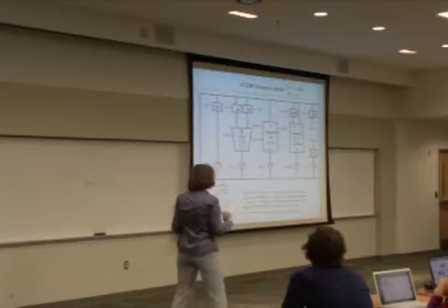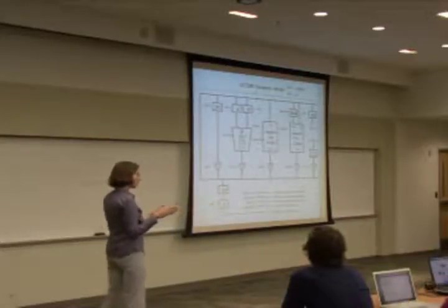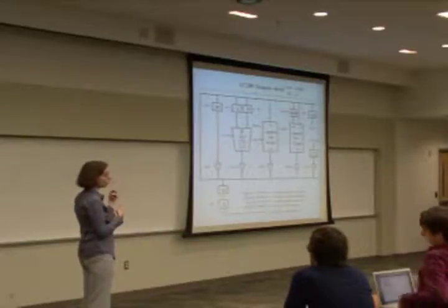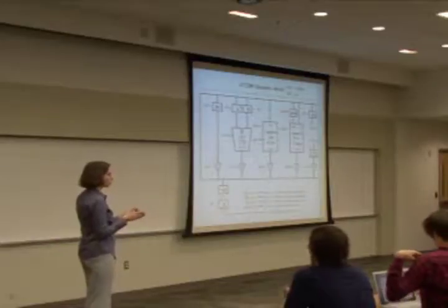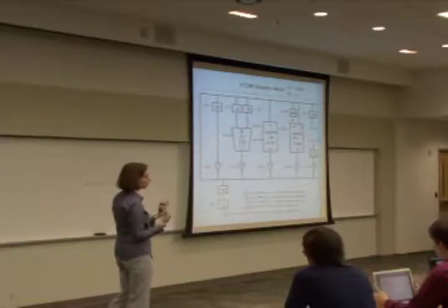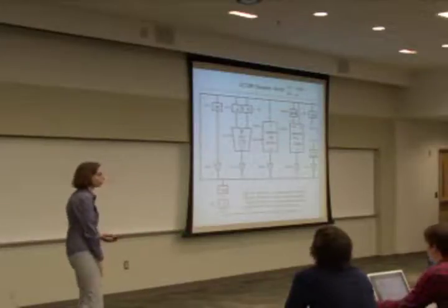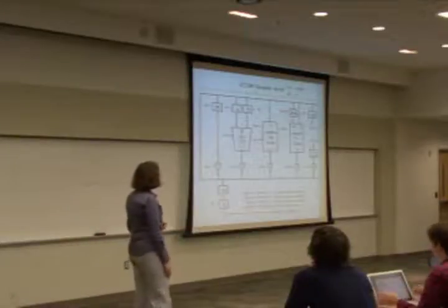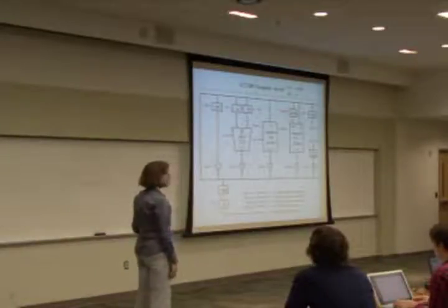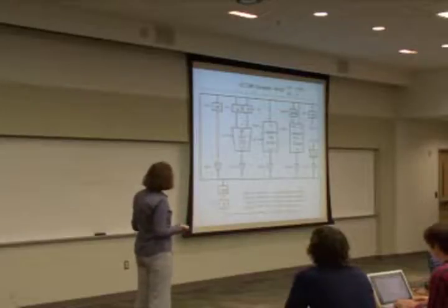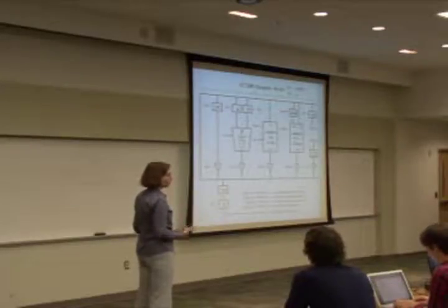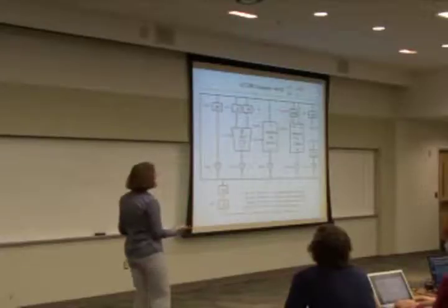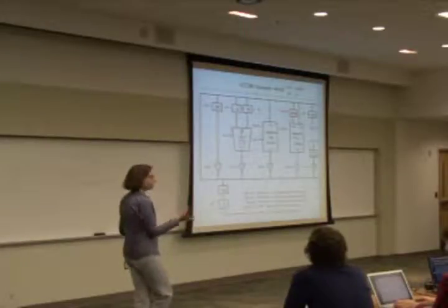Now, clock cycle depends on how you determine the width of how long one cycle lasts. So you can do a couple of these in one cycle if your cycle is long enough. If it's shorter, then you may do only 1 or maybe 2. So it's a matter of design. But these are the steps. So I fetch 1 would be this one. And the reason why you need 3 steps is because, again, you can write only one unit at a time on the bus. If you had 2 buses, then maybe you could do this step together with the first one. But you have only 1 bus, so only one is writing, while more of them can read.